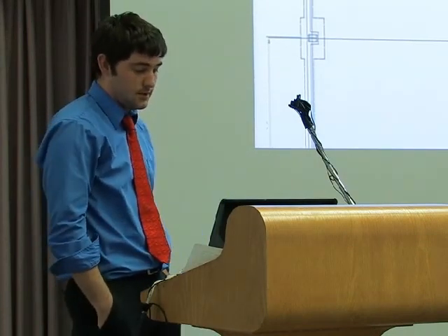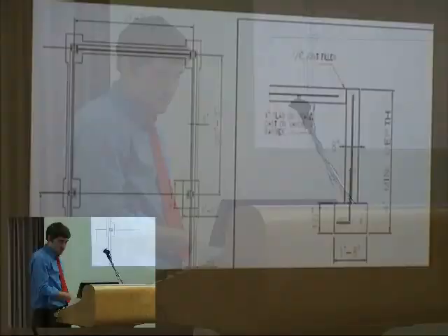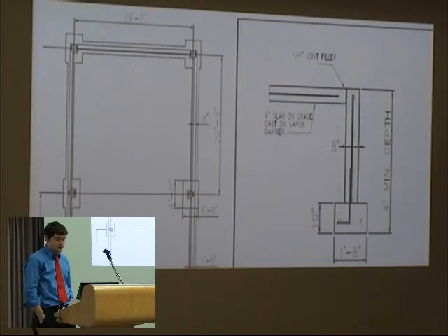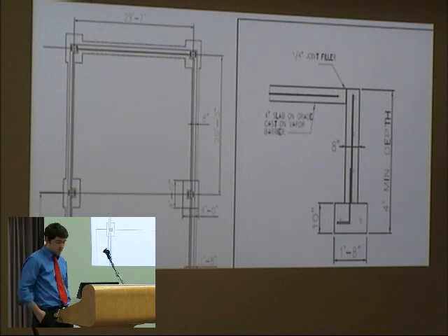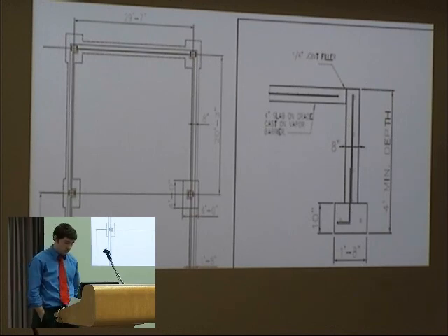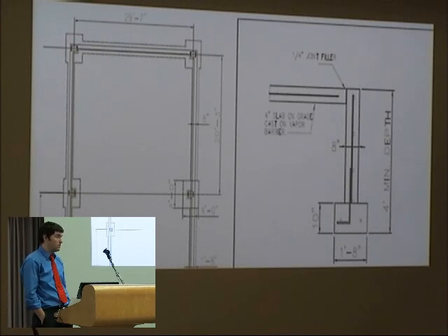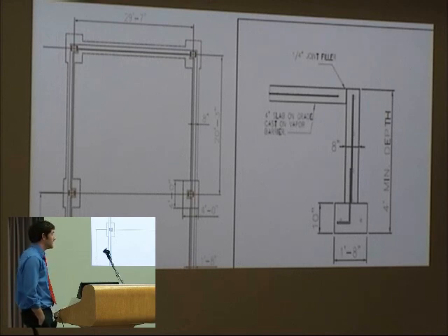Another thing we did as a geotechnical team was we designed the foundations for the buildings on site. We did this by getting the unfactored loads from the structural engineers, and then we combined them using LRFD load combination equations. And we used these max loads to design the footings themselves. We took into account the frost depth when designing the footing, so we made sure the base was below the frost depth, so that wouldn't be a problem. For our final design, we ended up with 4x4 square foot footings connected by an 8-inch bearing wall. And this is the foundation plan for the condo/retail buildings.